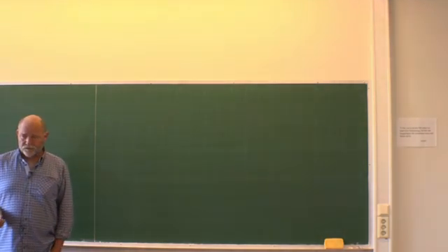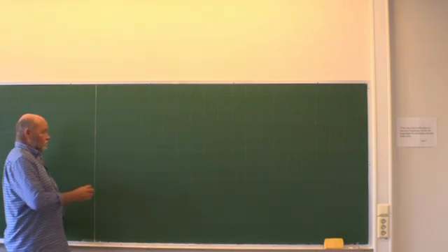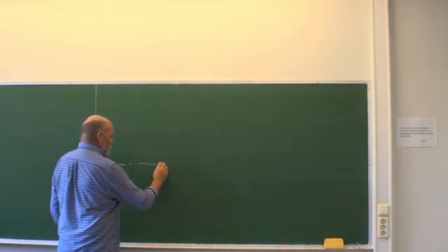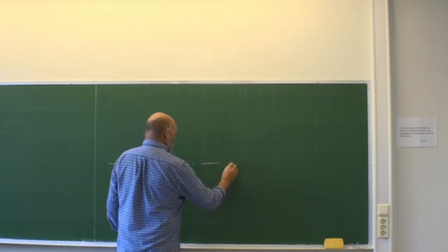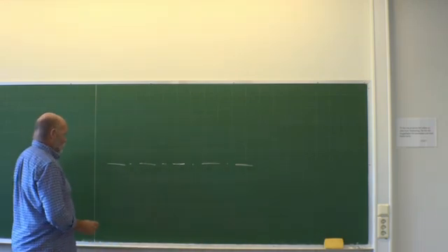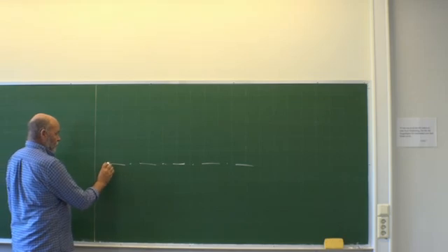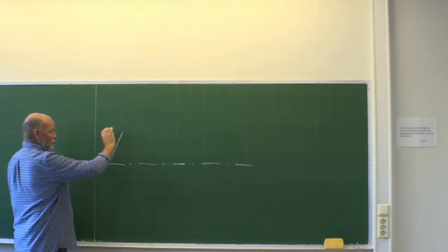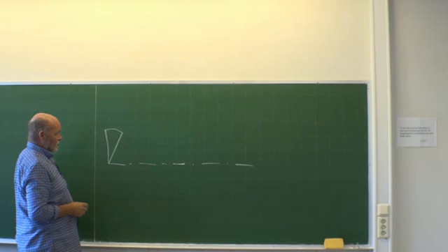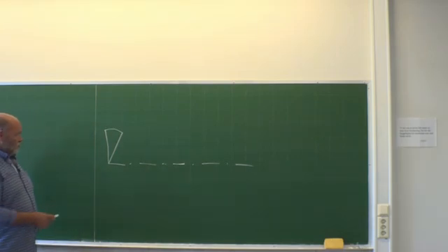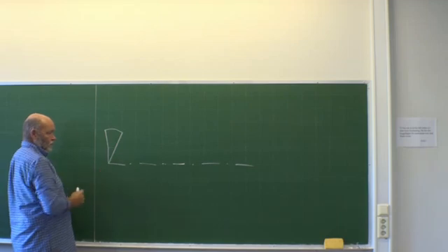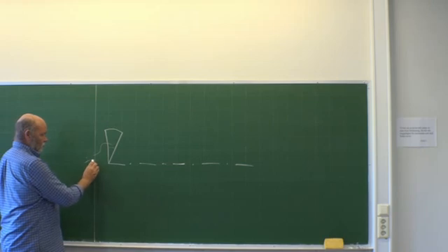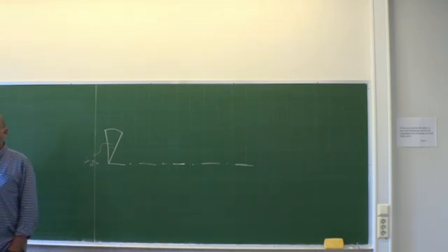So I have constructed the mesh as follows. Say here we have a symmetry line, something like that. And then we start here with a thin piece of cake. Let's overdo it a little bit, so it should be something like that. This angle, by the way, should be small, smaller than 5 degrees. I'll use 4.